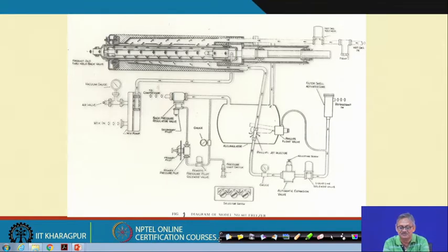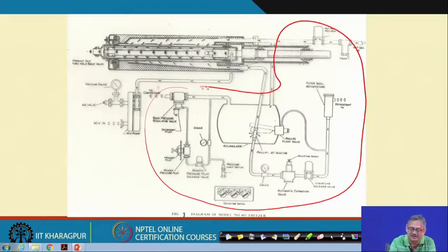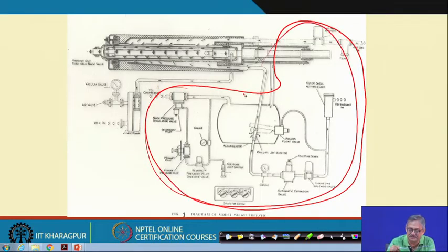What is it doing? If it is ammonia or freon 12 whatever, that is under this section, right. So, the liquid, either ammonia or freon, is then coming to the ice cream freezer, right. This is at the outlet, you see it is insulated, and the liquid is coming here, and this is called boil off technology, right.